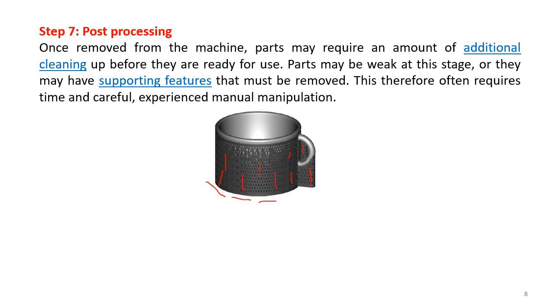So therefore it requires certain time and experienced people, so that an experienced person can remove them very easily, because they know which is the parent build material and which are the supporting material. So here a little bit of manual manipulation or manual intervention happens with the post processing.